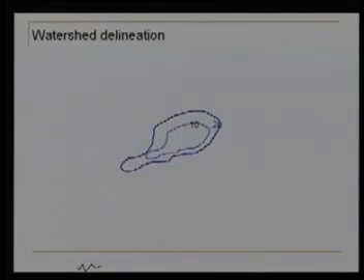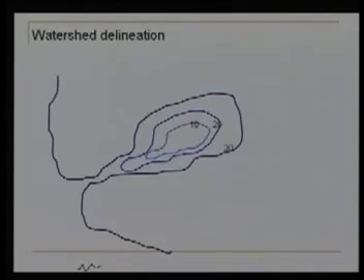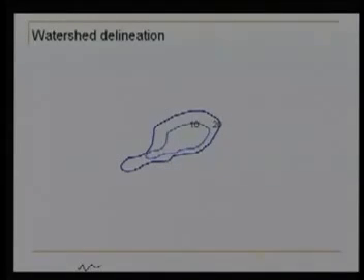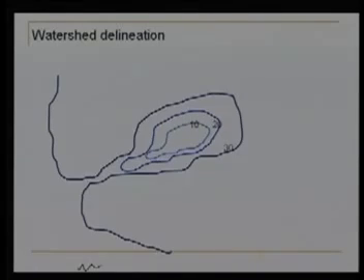The meaning is, at that cross section of the river, where all the water has come from. If you can locate that, that is the catchment area for this cross section. How to do that? Let us have a contour map first. The contour map in this case has the very first contour of 10 meter, 20, 30, 40. Now you can see how the ground is like. Just start feeling the ground. There is a little cup kind of ground here, then it is opening over here. The ground opens here.